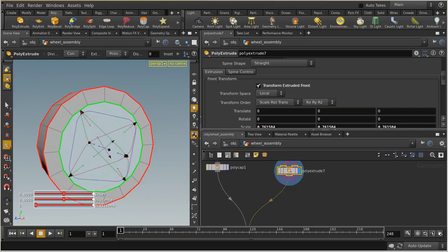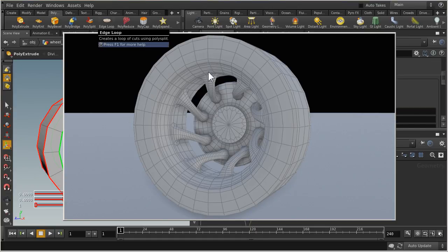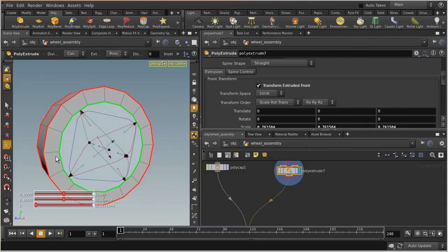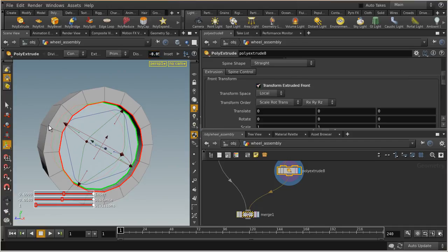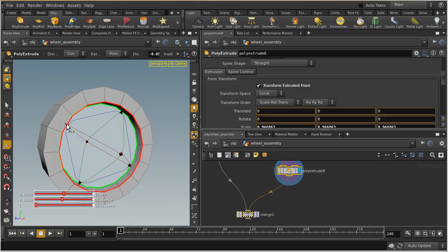And the next move we want to look at is sort of this little edge that dips in a little bit. So we want to extrude with a little bit of a scale and a little bit of a pushback at the same time. So let's make another poly extrude. Again, remember, since we just used that tool, all we have to do is tap Q on the keyboard. That automatically lays down a new poly extrude for us. So we want to push this in just a little bit. And I'm going to go ahead and scale it in just a hair as well.